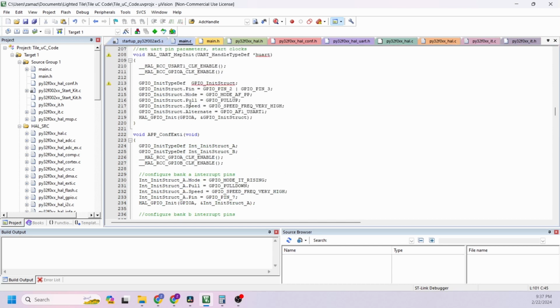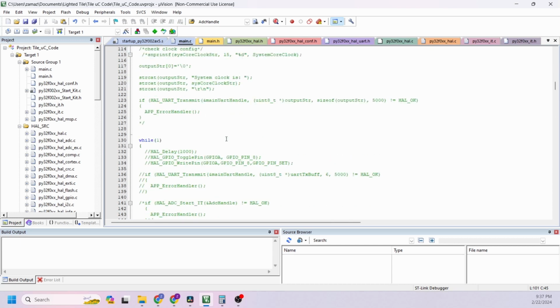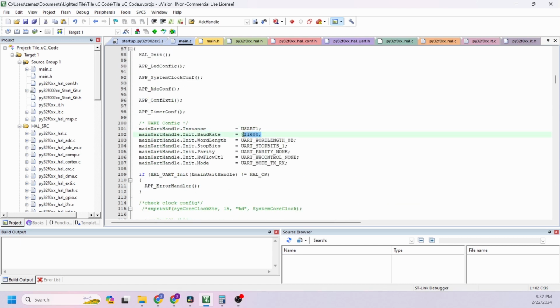The UART here is set pretty fast, 921,600 baud, so that the signal can be sent in time. This return value is also only 8 bits. Remember, this signal needs to finish sending in the time it takes the main controller to send 24 bits to command the respective LED, or it could overlap with another message and be unreadable.